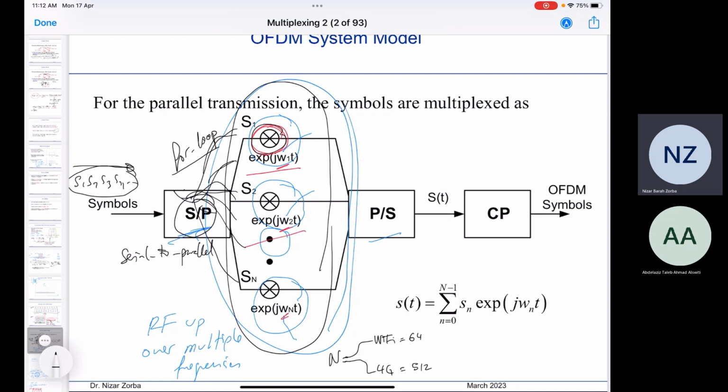Good. So now that we want to transmit, imagine 512 subcarriers. How many antennas does your mobile phone have? In the best cases, most probably two. So how then to transmit 512 frequencies over two antennas? This is why we have to put them back together. So this unit is simply an adder that will add each one of these, and then they are sent. If we look at the output of the adder in the time domain, we will see the signals overlapping on each other, indistinguishable.